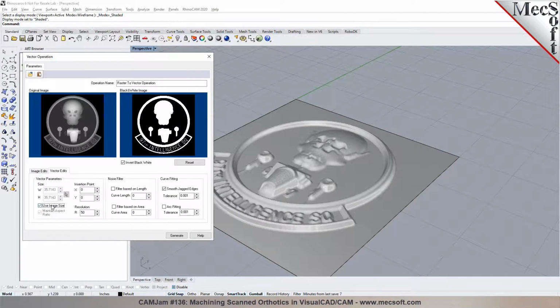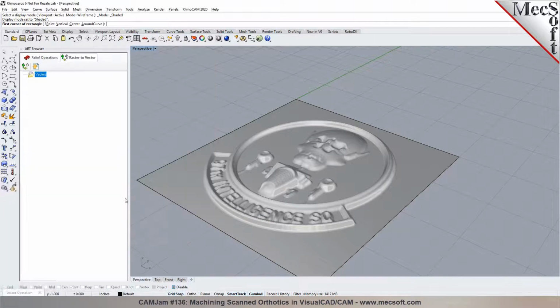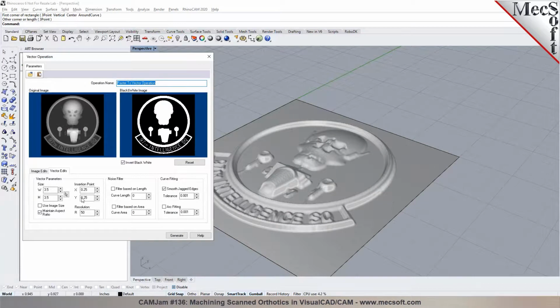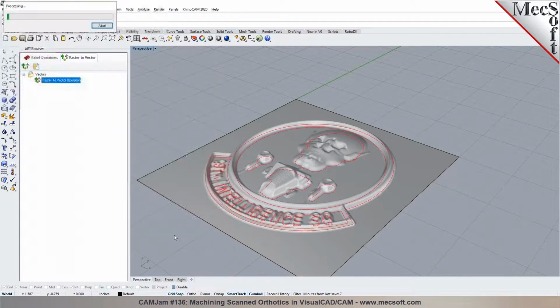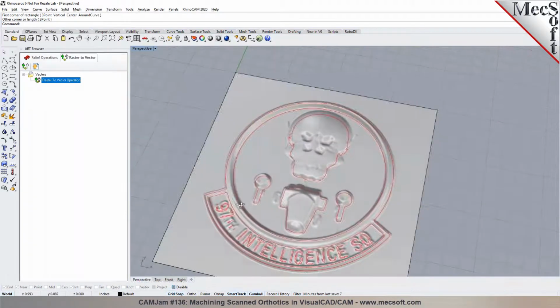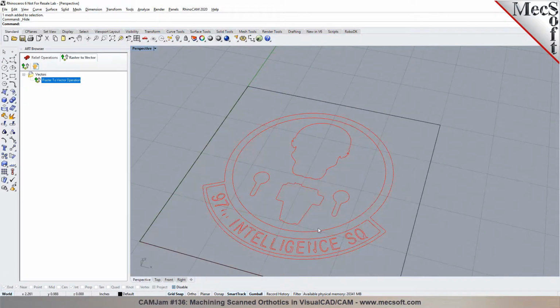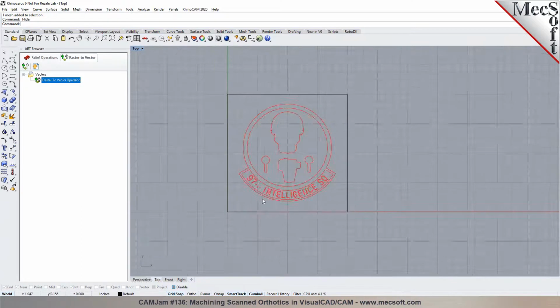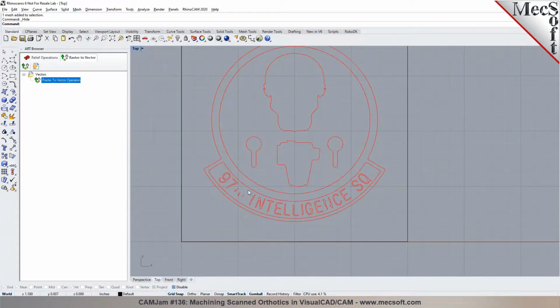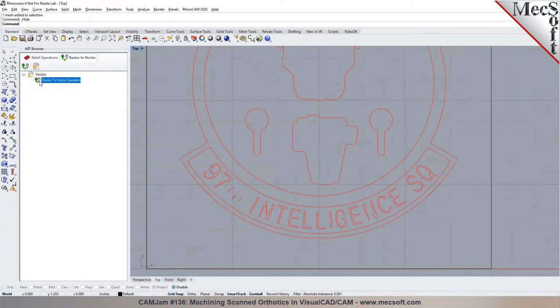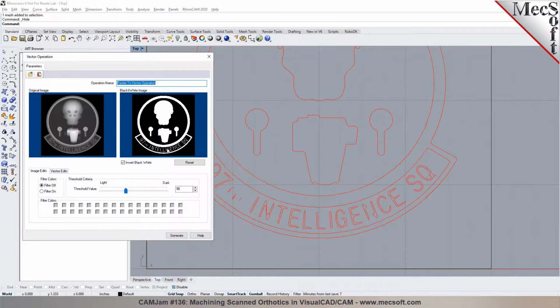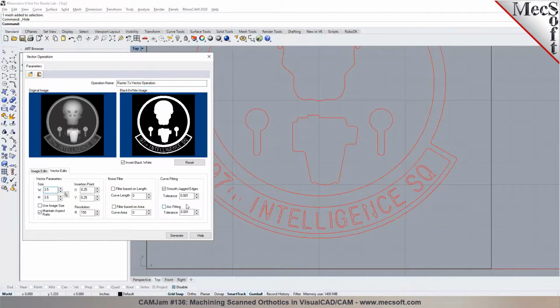And then I can go to vector edits. I can specify a size for it. Again, I can snap to these 2 points right here. And then I can set a resolution and then pick generate. So in this process, it's going to create those curves. Let me hide this so it's easier to see. So that was a raster to vector operation, creating those curves based on what's visible in here, and you can also adjust the smoothness.